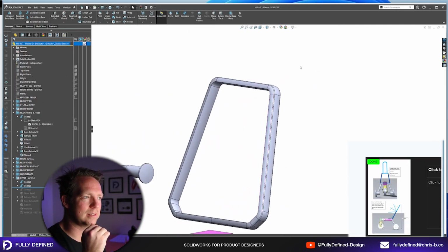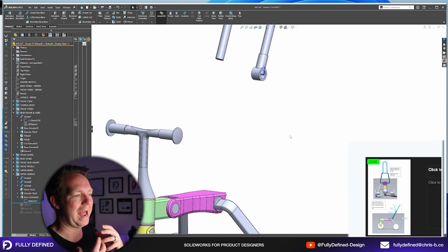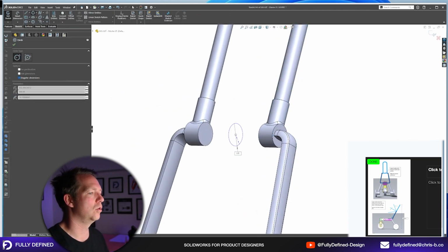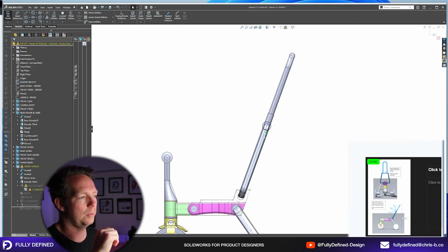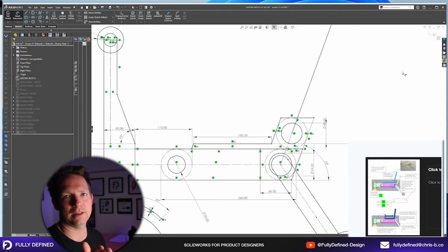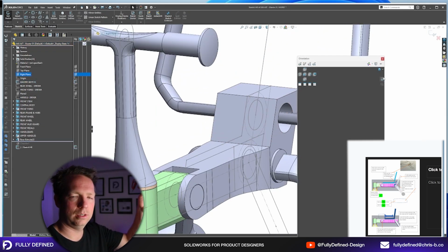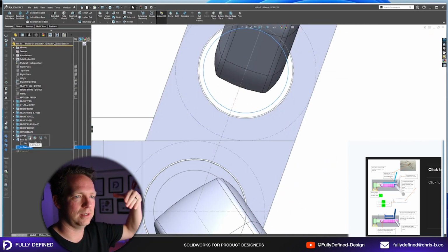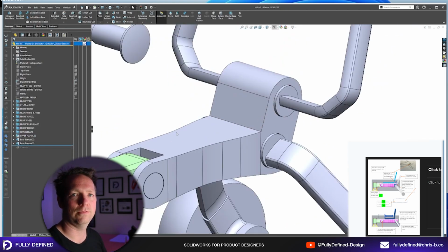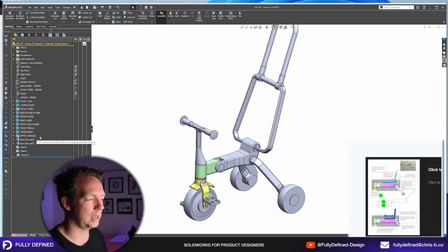You can then edit your master sketch and use those lines as reference points to add those details back into your master sketch. So you might convert the entities or just copy over the top of them, and then add your new dimensions that reference the other elements of your master sketch. Accept that sketch change, go to that previous sketch that's above, delete it, you no longer need it. Voila, you've got some newer features down in your feature tree, now controlling your master sketch.